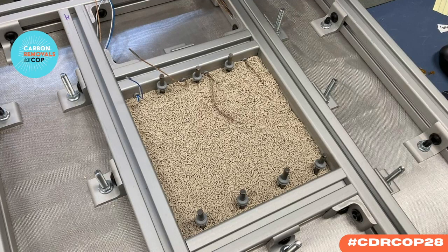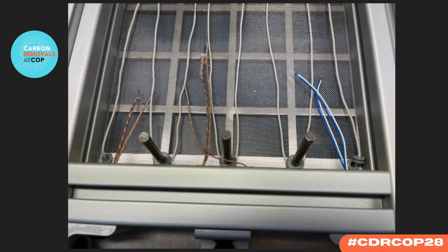Why are we heating up the sorbent? Well, that's what you have to do to make it release the captured carbon dioxide. It absorbs it, that is, captures it when the temperature is room temperature, but then when you heat it up, it releases it. So the system that we hit upon for actually warming the sorbent is with these heating wires that are built of nichrome wire, which has a fairly high resistivity as far as wire goes. And when you run a current through it, it heats up.